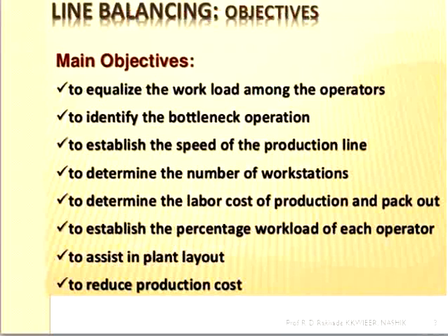Then there are certain main objectives of line balancing. So why do we require it? First, to equalize the workload among the operators. In most cases, the percentage of workload is not equally distributed among operators.